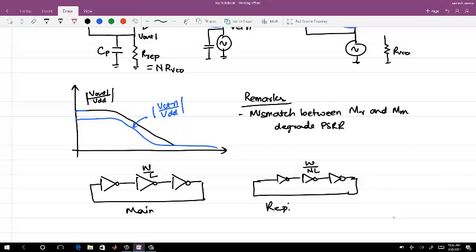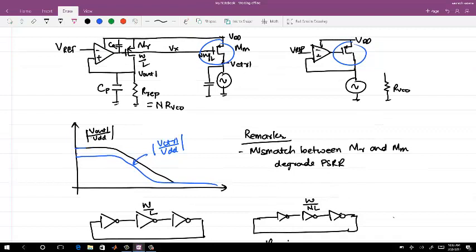The problem with the replica VCO is that the current which the replica VCO is consuming will be a switched current. So there will be a lot of glitches supplying here, which are actually there in the real VCO. You suppress them with the capacitor. The V control cap is not necessary.